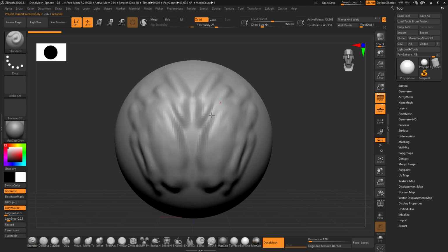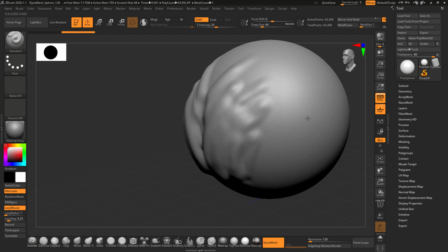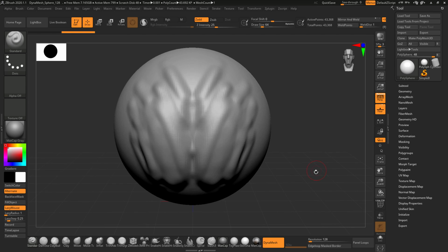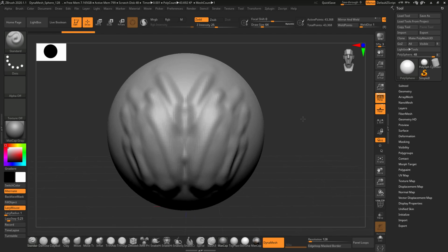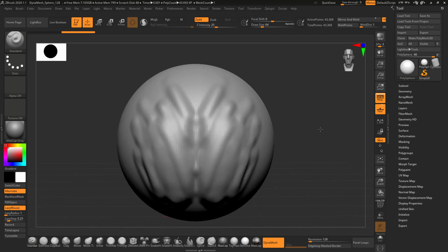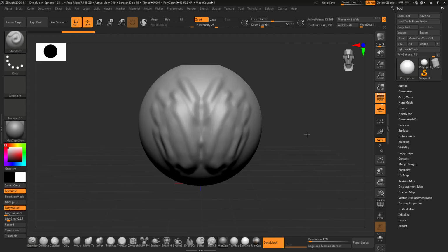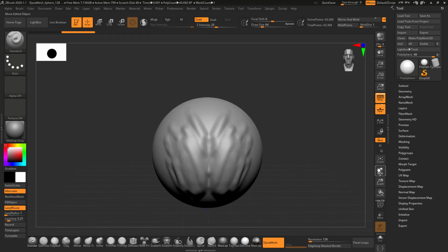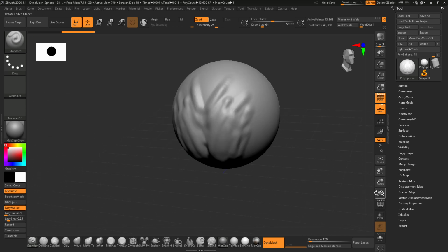And if you want to rotate an object, simply drag on the viewport outside the object and you can rotate the object, left to right and top to bottom. If you want to pan it, simply hold Alt and then drag. And if you want to zoom in, zoom out, then while panning, release the Alt. Same commands you can follow from here. So you can actually move the object, you can zoom in, zoom out, and you can rotate.